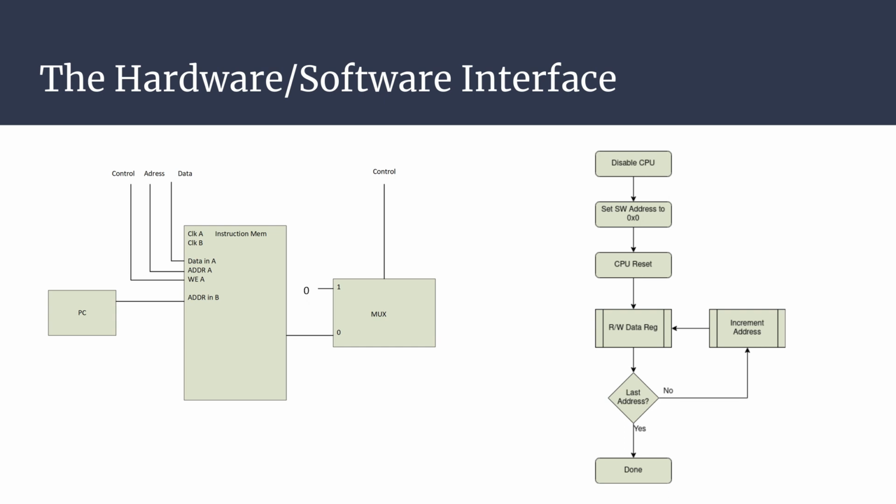And that's essentially how we also do our data memory interaction. So when we set our data memory, and also when we read from our data memory in our CPU. Now it's also important to note that when we're interacting with our data memory, we have to disable the output of our instruction memory, so instructions do not pass through the pipeline and interact with our data memory.